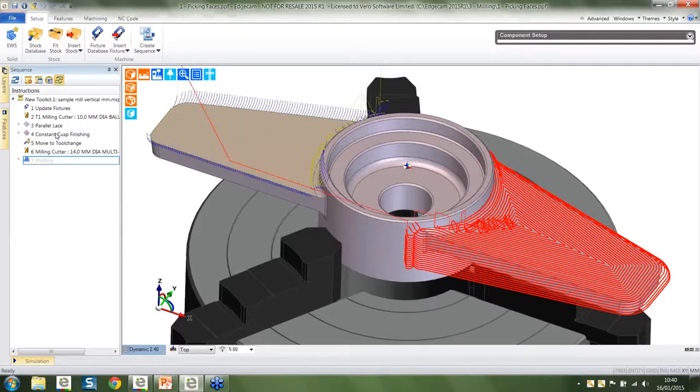So we know that when we machine in Edgecam, we pick faces or we pick the whole of the solid body, but by inference that means it's going to machine all the solid body or all the face, so we tend to use containment boundaries, and that means us having to prepare things.